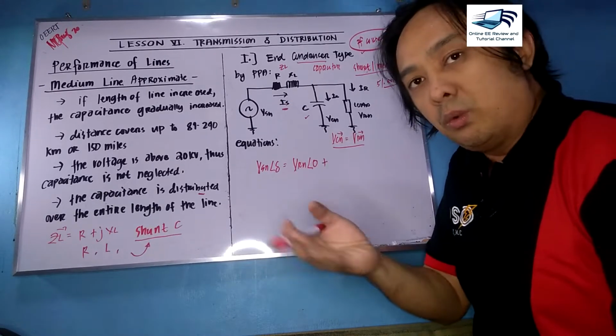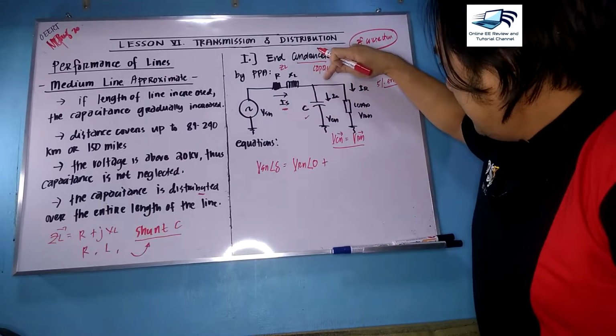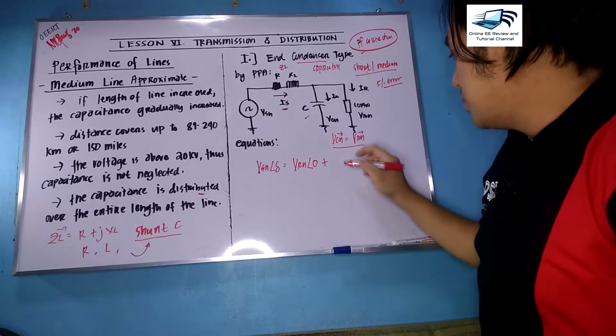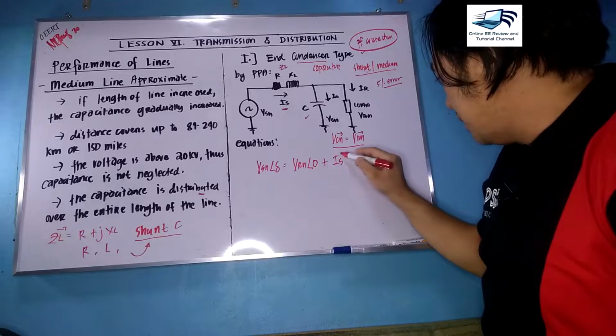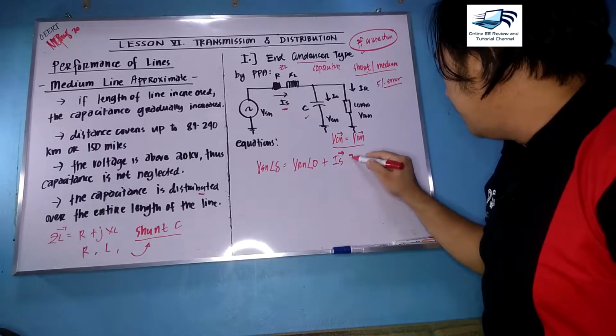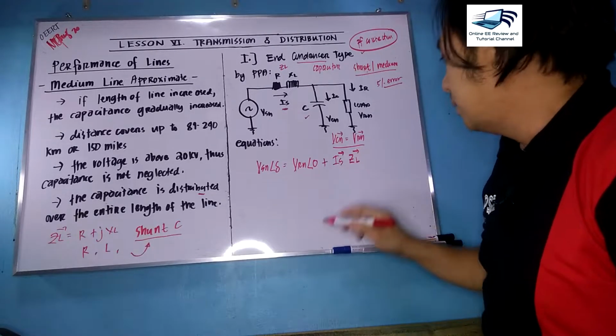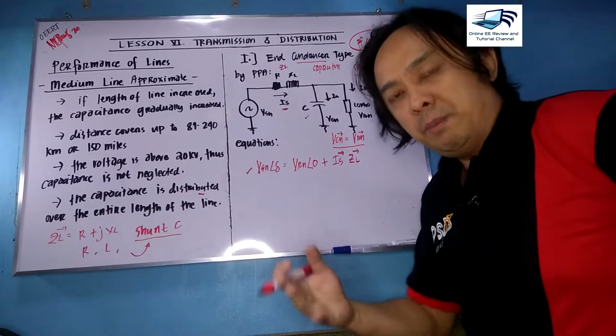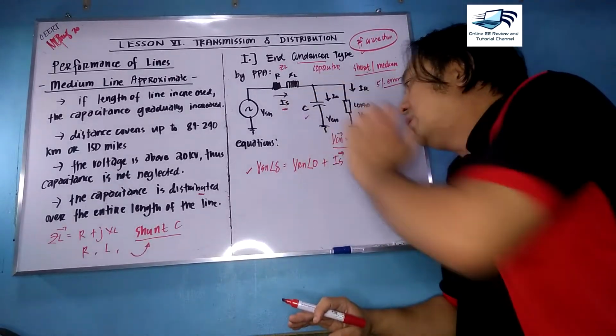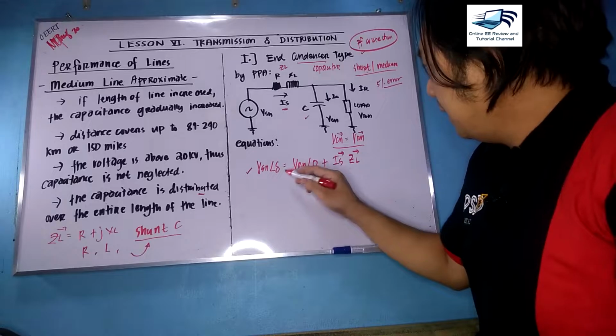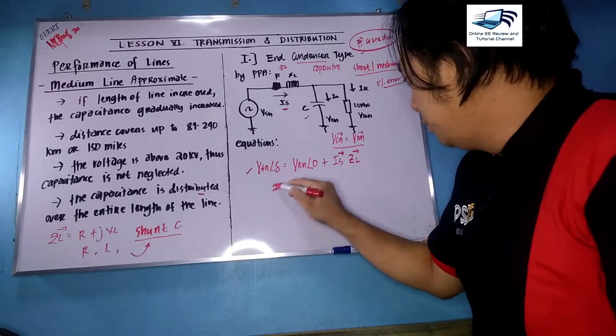It does not equal I, simply because your IS is IC plus IR vectorially. So you need your IS vector multiplied by ZL vector. I did not memorize anything here, I just use circuit analysis, and then your IS can be computed.